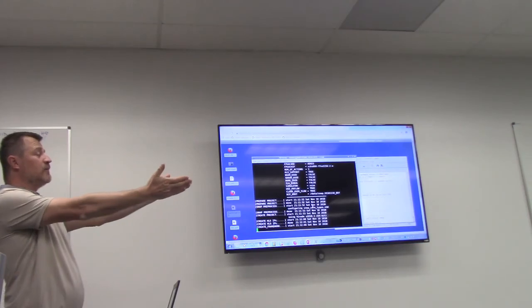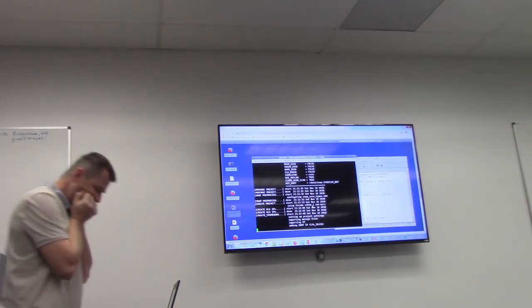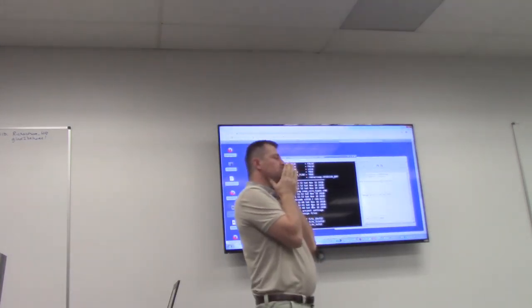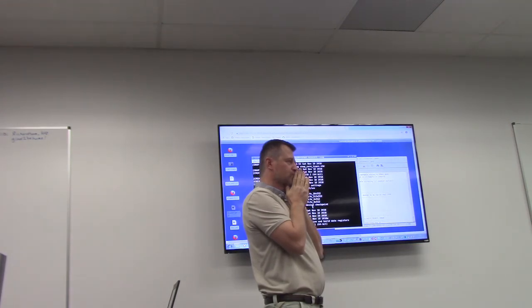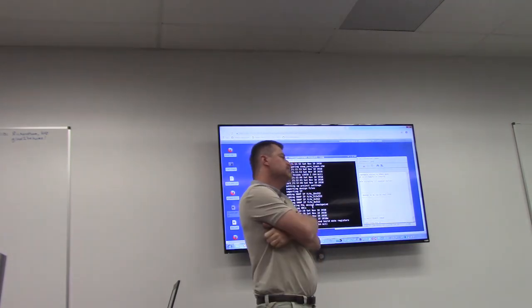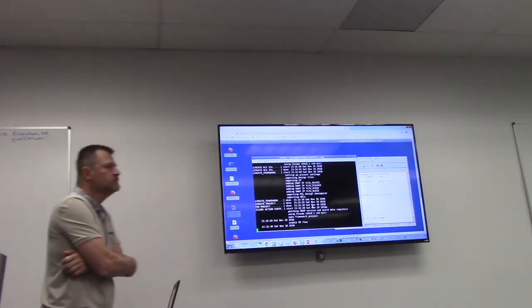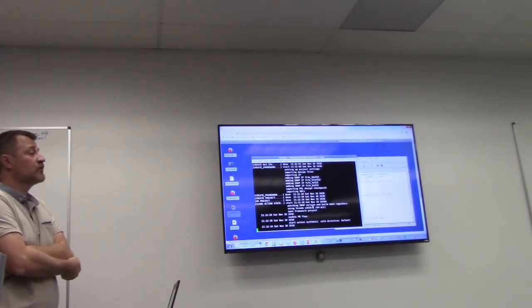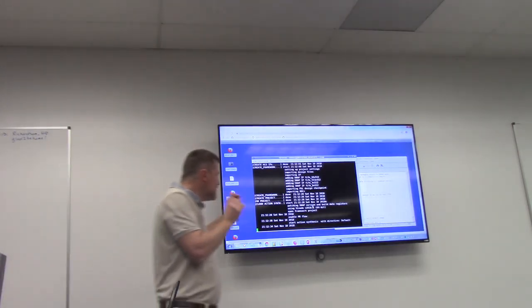Can I comment on that? Please. Because I can explain. So the reason is that this method is full configuration of the FPGA. So we want to make sure that if there's a mistake in the bit stream, it doesn't cause the FPGA to have to be reset with JTAG, to where somebody would have to go to the data center and do it. So in partial reconfiguration, that's usually not an issue. But in this, we built this specifically to verify that the images are good before they're actually deployed. And it's worked quite well. So it's a specific, very, very teeny difference.